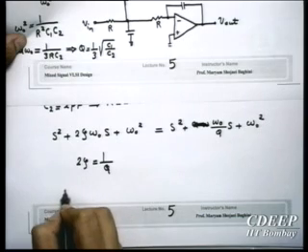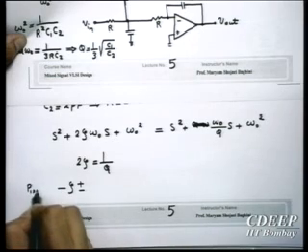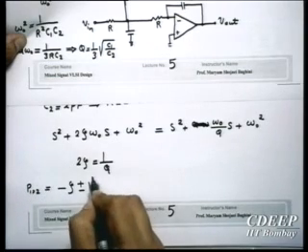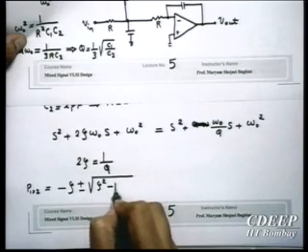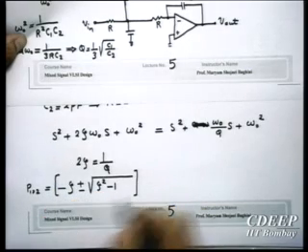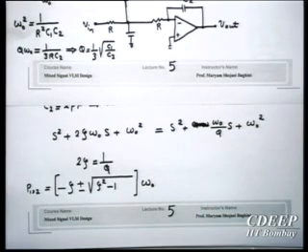What are the poles? p1, p2 is minus zeta plus minus root of zeta square minus 1. The entire thing will get multiplied by omega 0. So when Q is equal to 1, it means zeta square is equal to 1 upon 2.